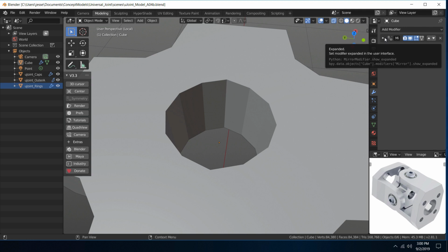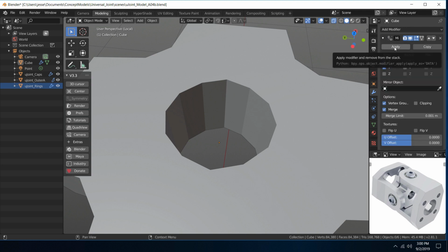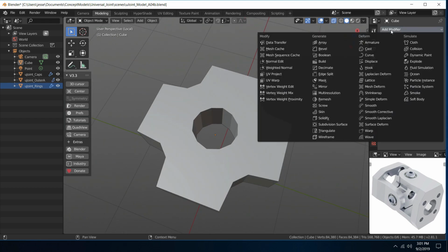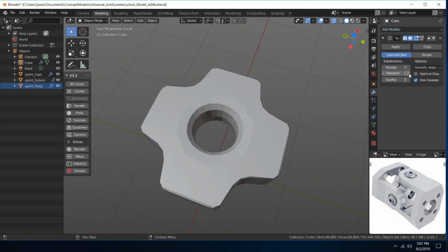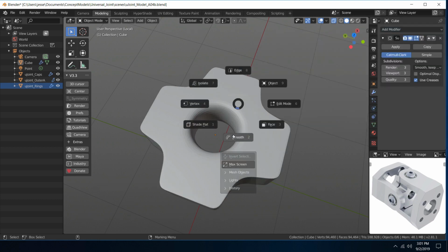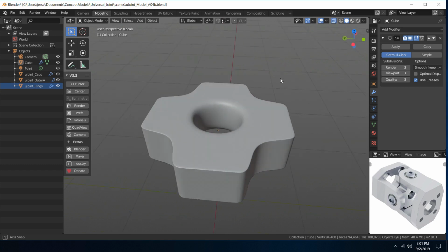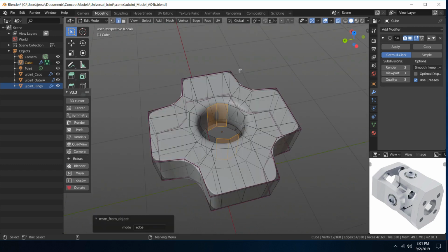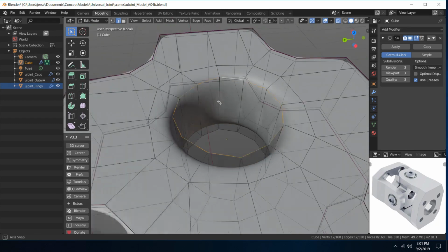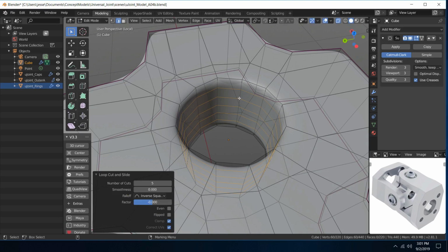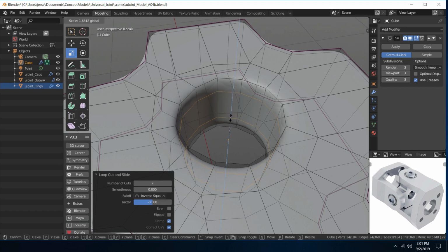And now that we've gotten that far, let's go ahead and apply the mirror. Let's see if it merged those vertices for us. So subdiv and smooth. Yeah, looks great. Okay, so now we just need to harden those edges. Let's right click, click off, and do 2 segments, and just as usual, we'll just scale.